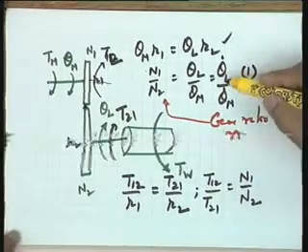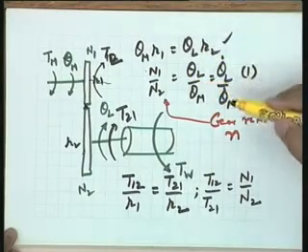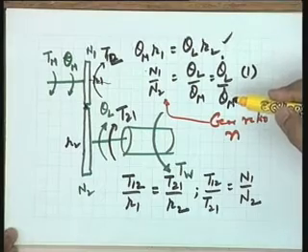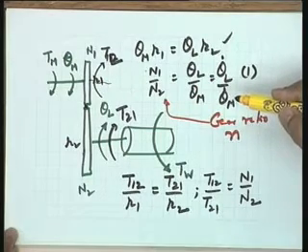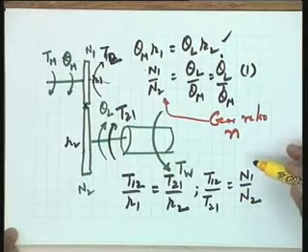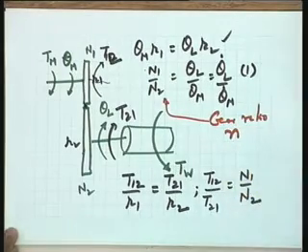If you take 1 by 30, you find theta L dot is equal to 1 by 30 into theta m dot. It means the load speed has reduced by a factor equal to the gear ratio. Now T12 is 1 by 30 of T21, so T21 is equal to 30 into T12.